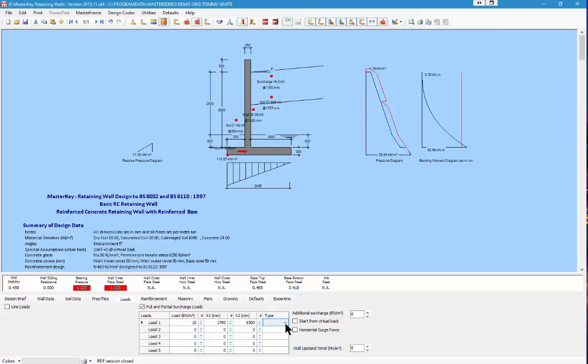One of the things we never talked about here was actually what type of load it is, and that would be quite significant in whether it's a dead load or a live load, because that would be quite useful to know from the loading point of view. Not that critical until we get into the highway loading on the structure.